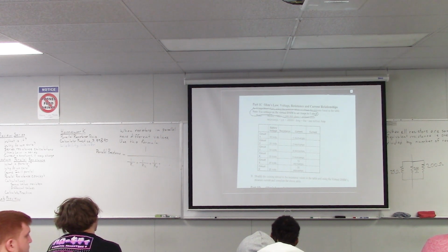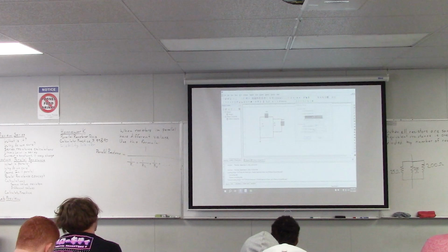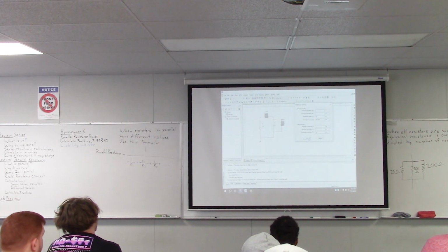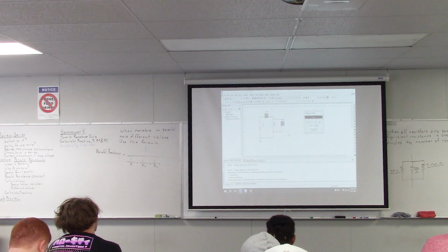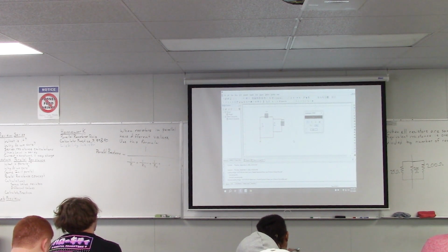So when you come to this part of the lab, you're gonna stop that. You're gonna open up the settings on this multimeter, and you're gonna change the ammeter resistance to 1 ohm. Right now it's set to 1 nano ohm. You just change that to 1 ohm for that part of the circuit only. Okay? For that table in the homework, in the lab. All the rest you leave the same, but just for that table in the lab you change the setting. Okay? So are there questions there? All right.